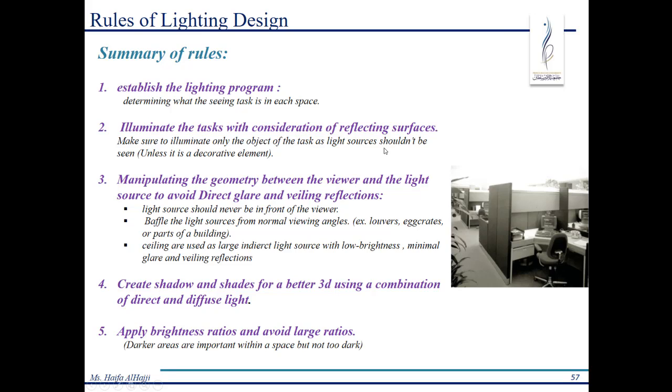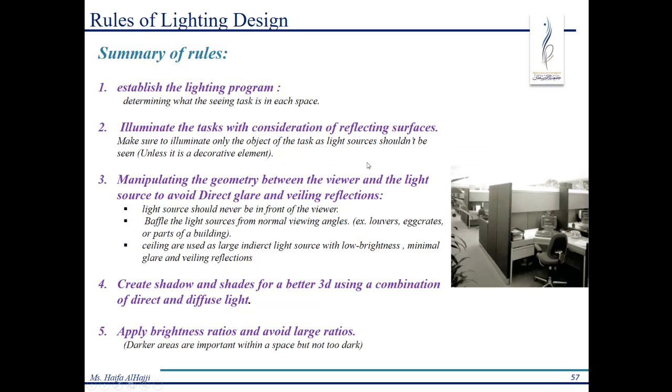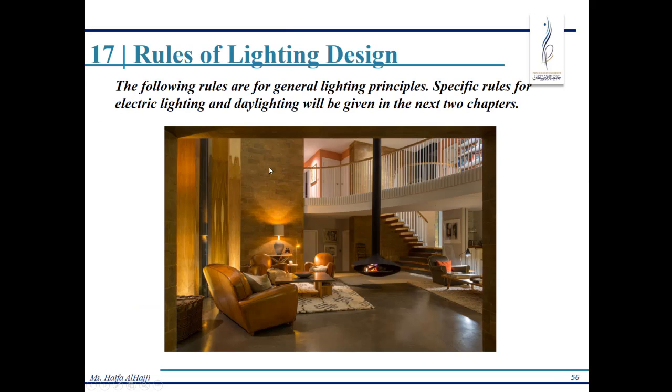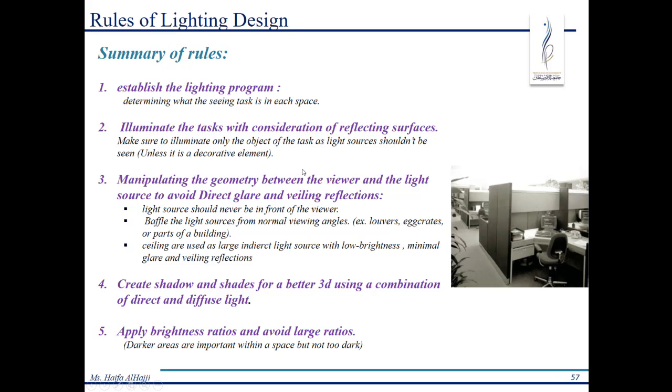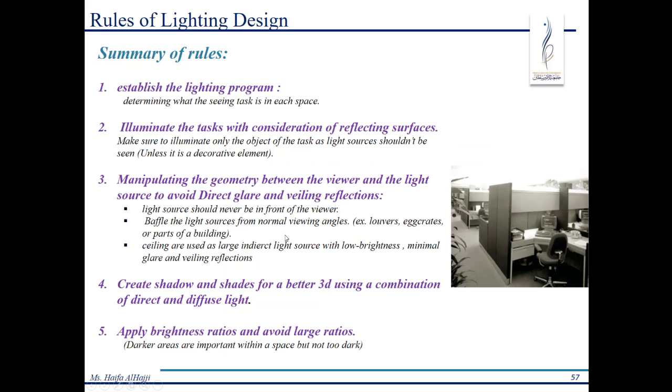So quality is to avoid having a low brightness ratio or a high brightness ratio. So you need to take into consideration the reflectance factor of the surfaces, to reflect more light. And if you make them a light color, you are increasing the brightness in the area at a low cost instead of adding lamps. For example, in this condition, if this was beige, it would be better than adding a lamp, maybe a high-level lamp in here.